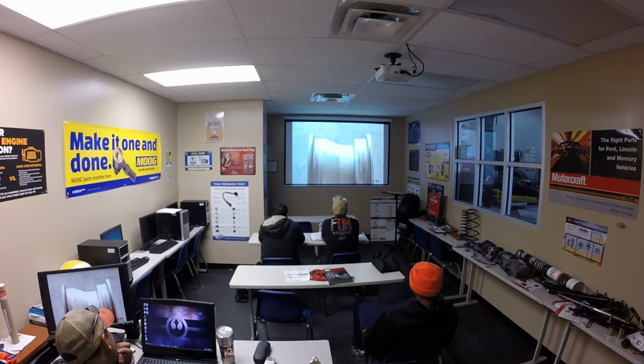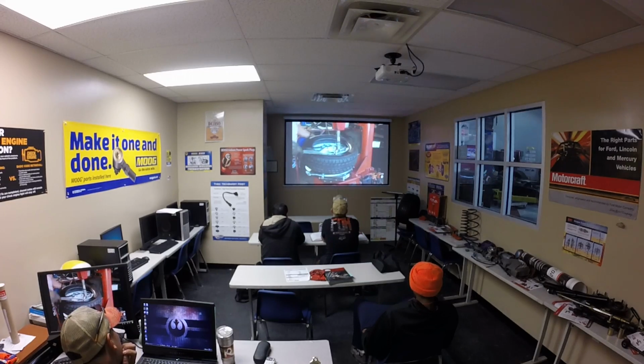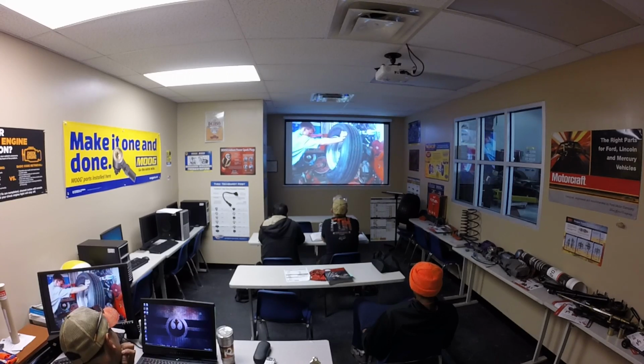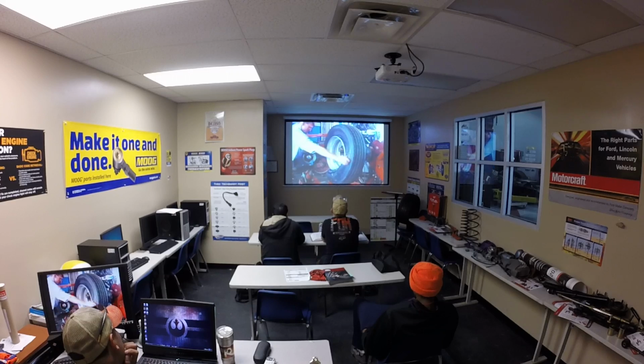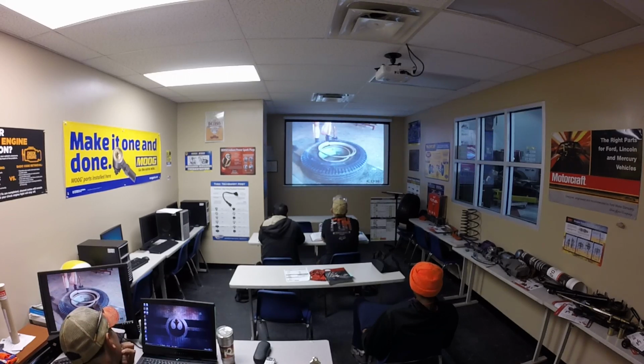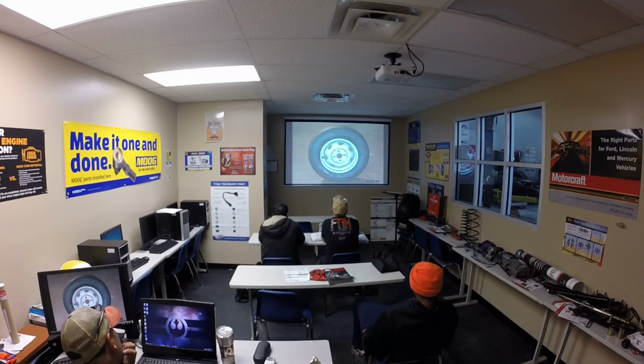Most passenger car wheels are of well or drop center design. This design allows for tire removal and fitting. Tires for heavy goods vehicles are much stiffer, but they can also be fitted to a well-based rim or to a flat-based detachable flange rim, depending on construction. To ensure correct fit between a tire and a rim, all manufacturers of wheels and tires comply with standard dimensions, as recommended by tire and rim associations.